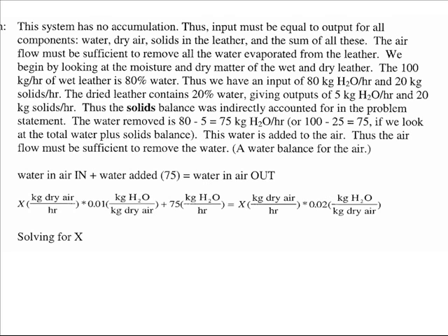Here from the book is the solution to this problem. This system has no accumulation. Thus, input must equal output for all components: water, dry air, solids in the leather, and the sum of all these. The airflow must be sufficient to remove all the water evaporated from the leather.